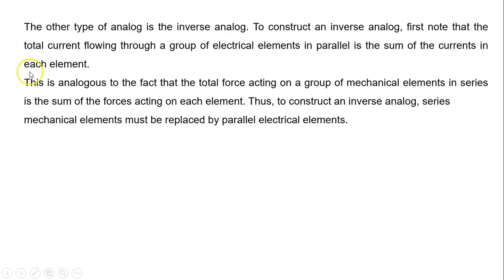This is analogous to the fact that the total force acting on a group of mechanical elements in series is the sum of the forces acting on each element. Thus, to construct an inverse analog, series mechanical elements must be replaced by parallel electrical elements.